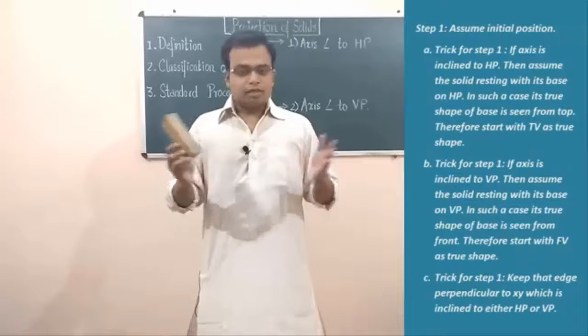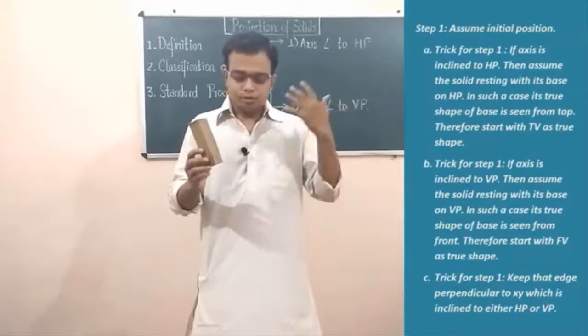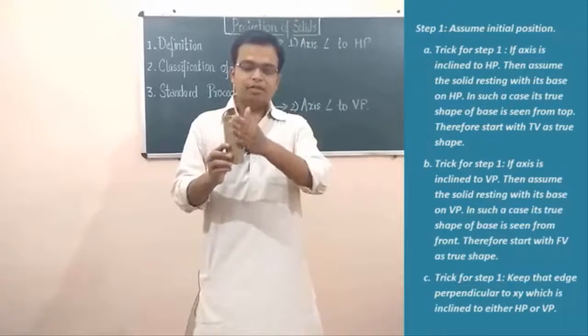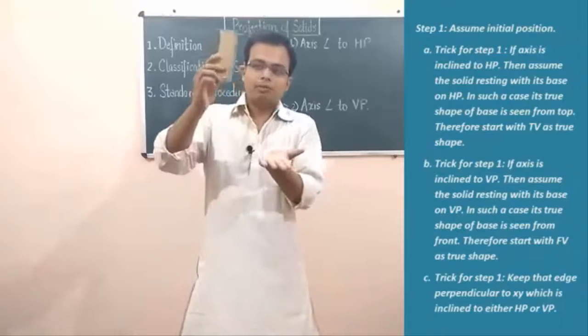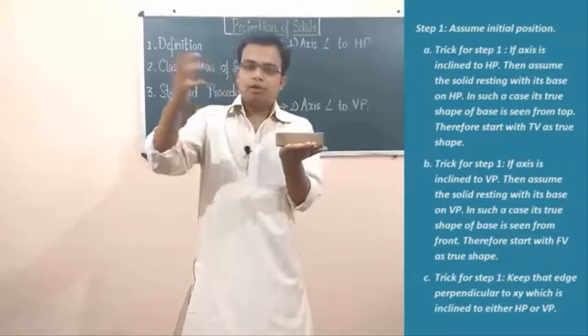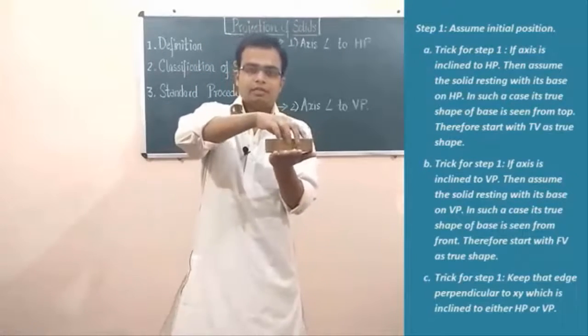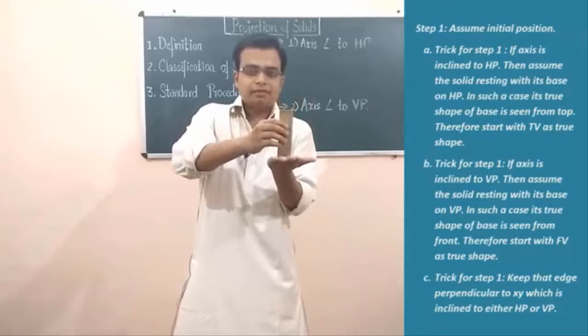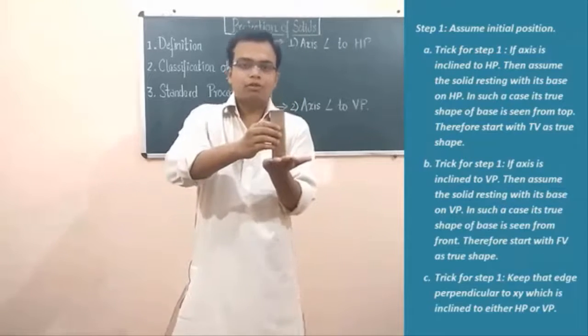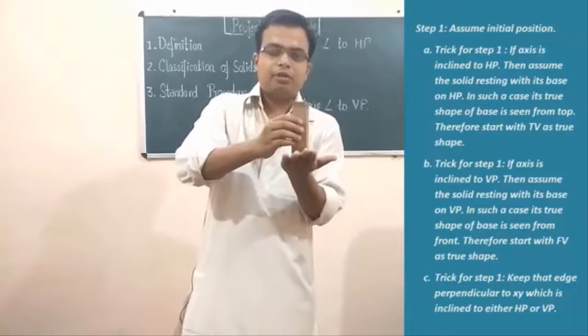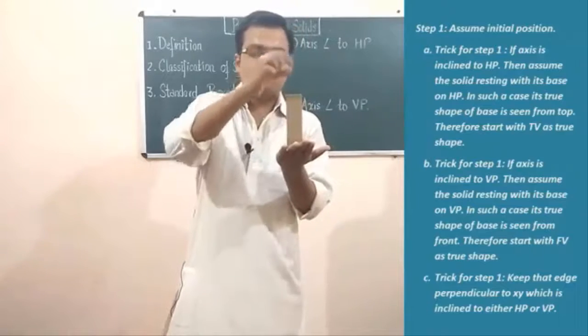Always remember, whichever edge is inclined in step number 3, it initially has to be kept perpendicular to XY. That's it. Now there are certain cases that you have to deal with in which you'll find that a face is resting on the HP. Then what are you going to do? In such a case, initially you have to keep it standing. Then again you need to ask yourself, from where can you see the true shape of this base? Obviously from the top.